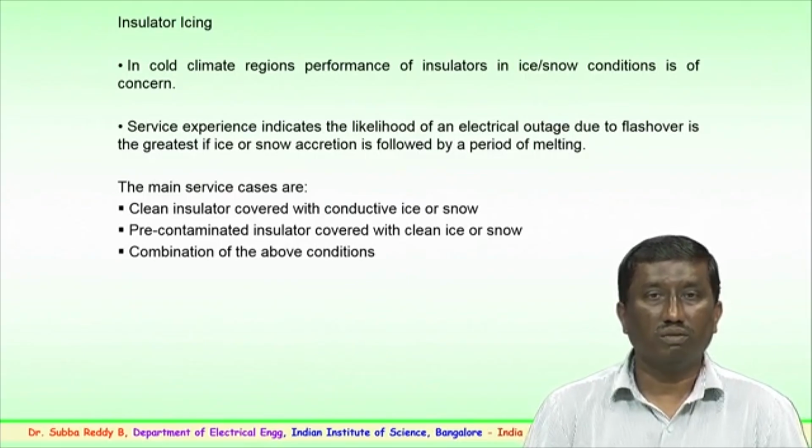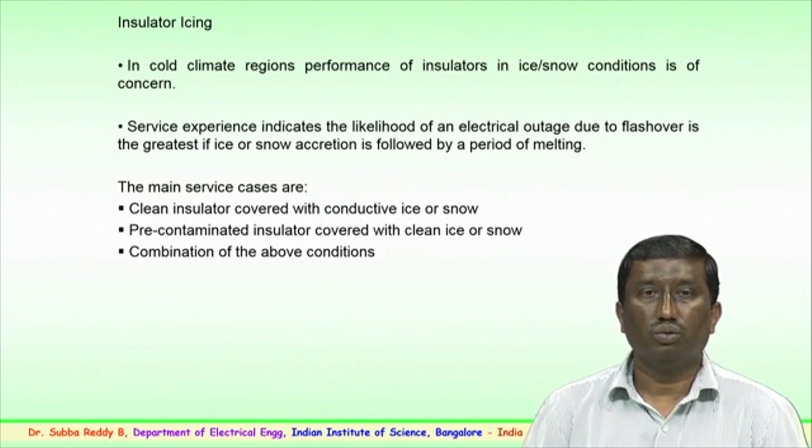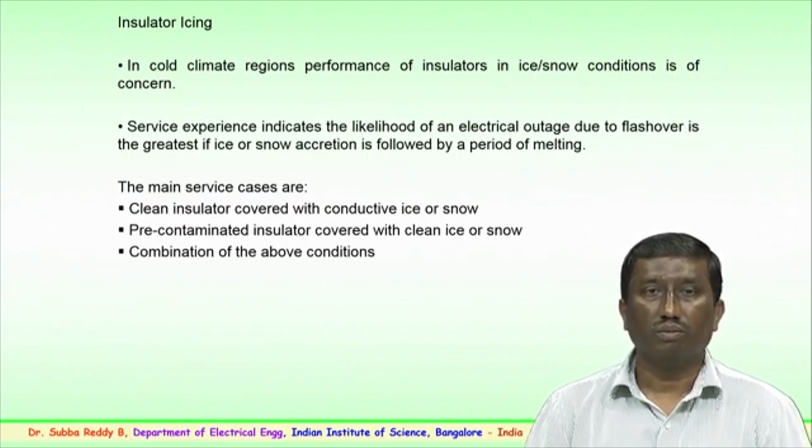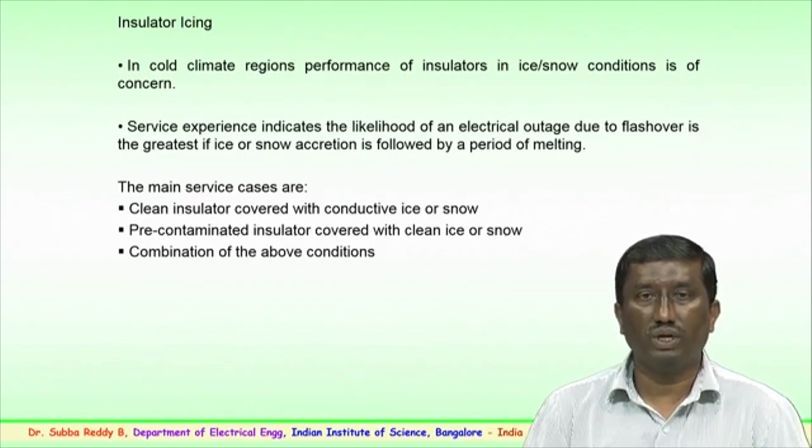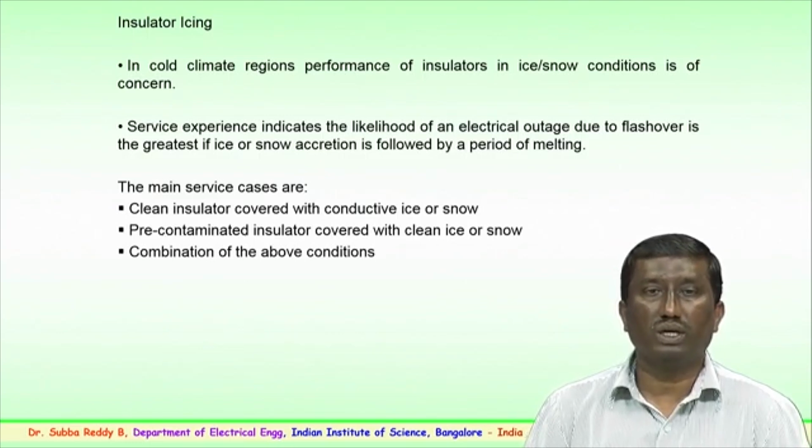So, the main service cases to be attended to are to clean insulators covered with conductive ice or snow, pre-contaminated insulators, or polluted insulators covered with ice or snow, or a combination of the above conditions.